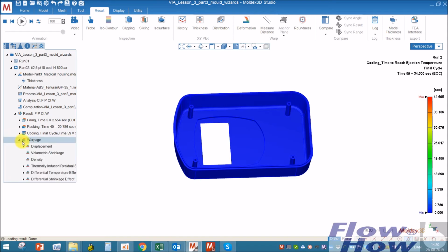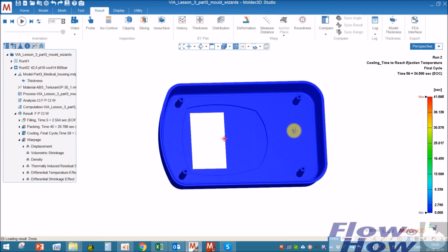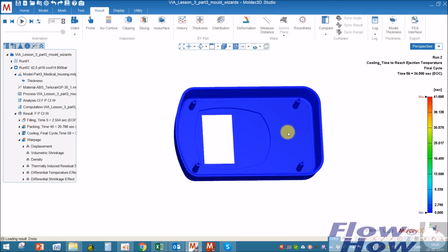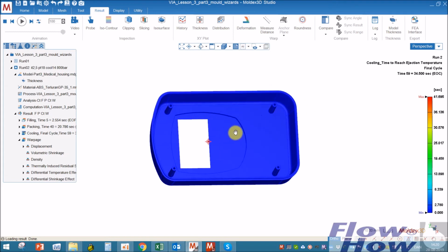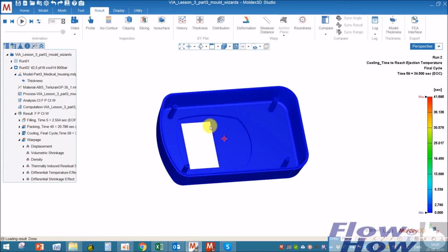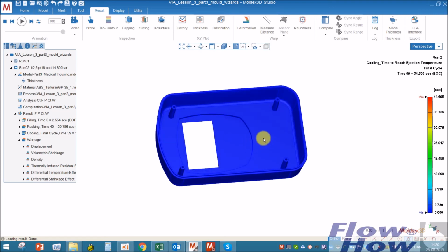The last thing I will comment on here is the warpage, because one thing is that you have made a CAD part that is correct and you can mount together with all the other parts, but when you run an injection molding process, something happens. Of course, because something happens with the plastic because you get differential shrinkage all over the part.